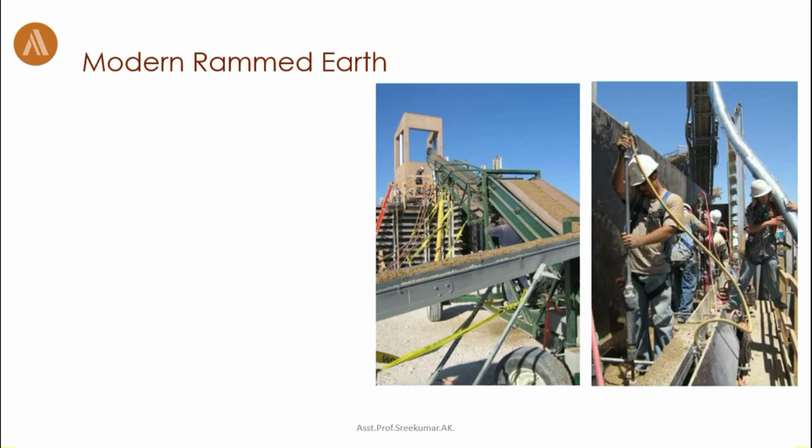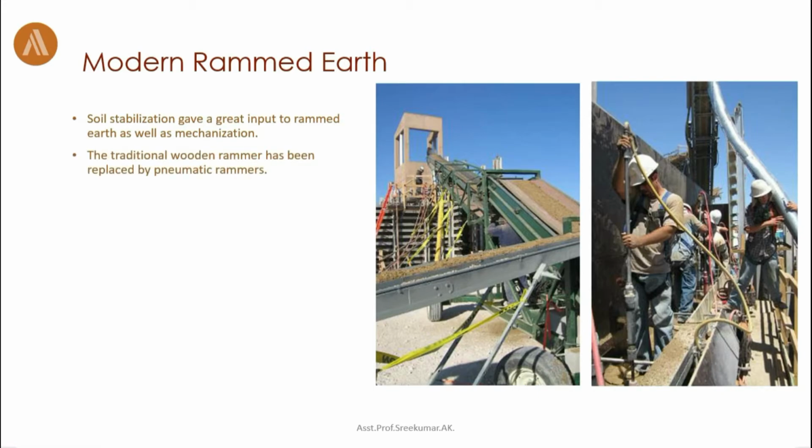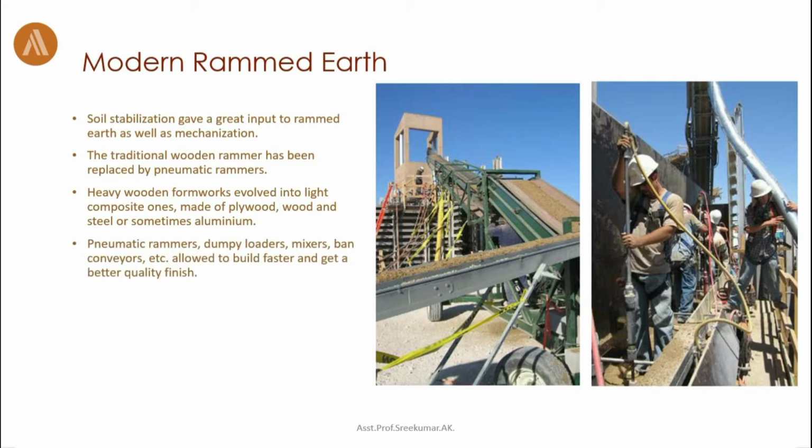Next we have the modern rammed earth techniques. In this system, soil stabilization gave a great input to rammed earth, as well as mechanization. The traditional wood rammer has been replaced by pneumatic rammers. Heavy wooden formwork evolved into light composite ones made of plywood, steel or sometimes aluminium. Pneumatic rammers, dumpy loaders, mixers, bank conveyors, etc. allowed building faster and getting a better quality finish.